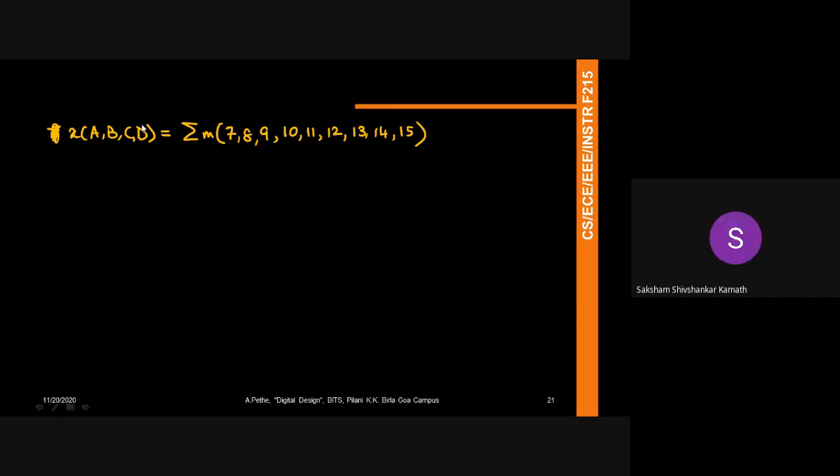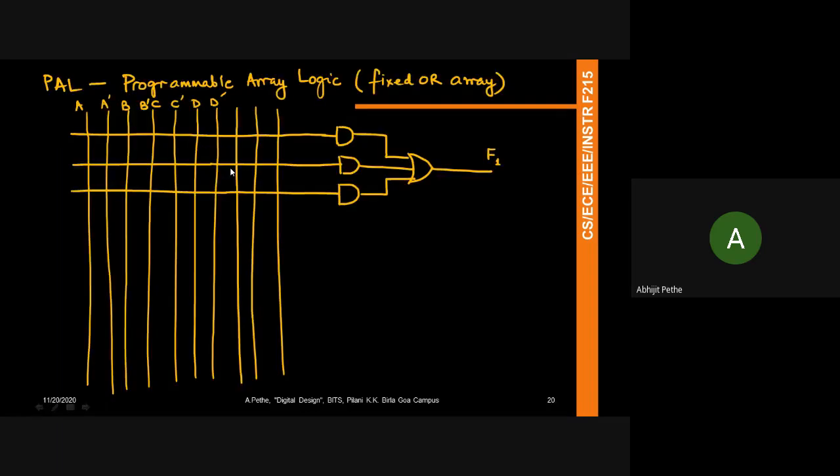A plus BCD. Very good. So this can be written as A plus BCD. What you see is X consists of two product terms in the sum-of-products form: one is A, the other one is BCD. So I can implement it in this. And how would I implement it?